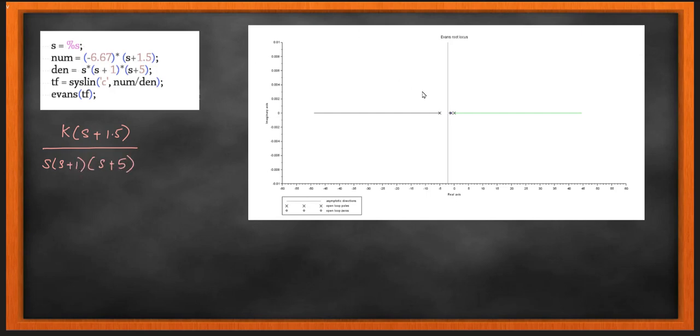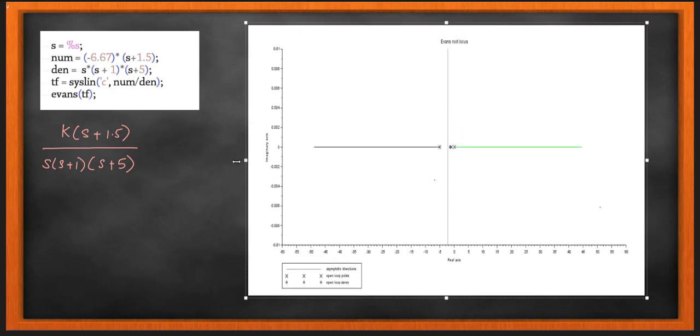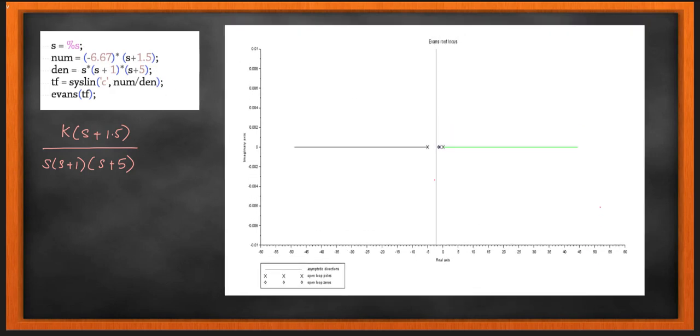So when you have an easy question like this, you don't have a breakaway point. Because your asymptote, the gray line, is at 90°, so it is perpendicular, which means you don't have the breakaway point. Your poles and zeros are plotted, and not much else is there, because it's a very easy level question. So your root locus looks something like this, and then the root locus on the real axis can also be done. You do that.